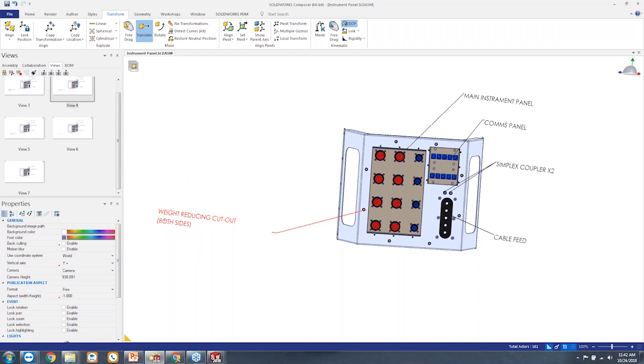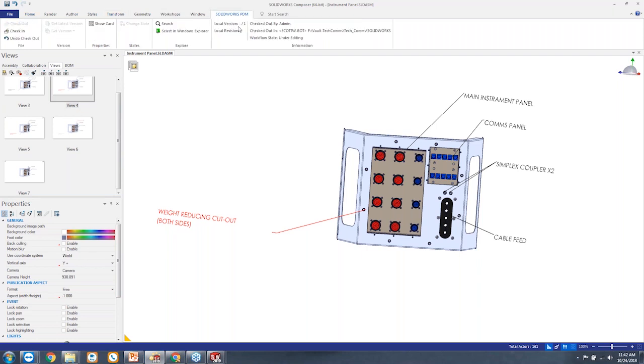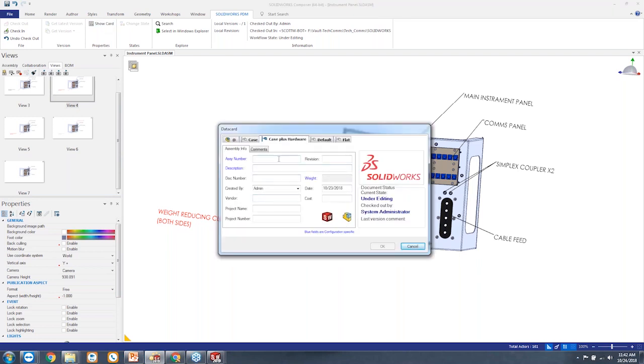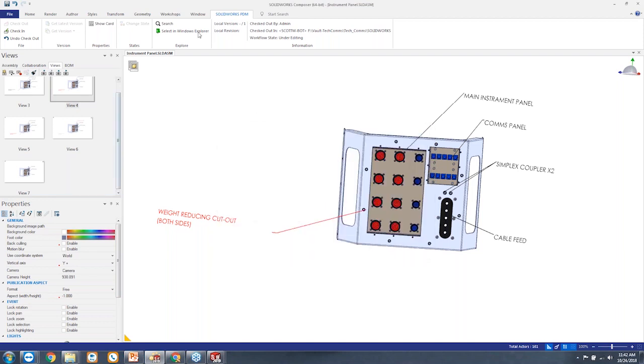Okay, and let's talk about the 3D library. So, oh, you know what? Before I do that, let's do one little more on PDM here. Because we opened it from PDM, you'll see that there's a tab for PDM in Composure. And now, which is awesome, we could check this in. We can show that there's the data card, so we can actually write. This just doesn't have the PMI data, but we could add PMI data to actually write into the cards. We've got a data card just like for Inspection, but for Composure, and I can check this into the vault.